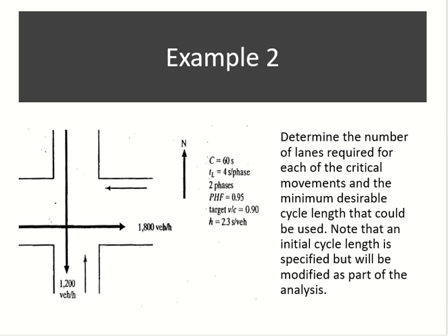Right now we are saying one lane here. So if there are 1800 vehicles, all of them will pass from one lane. So they will pass one by one. So all 1800 of them need some signal time, right? Clear? But if I make two lanes here, then I can pass two vehicles at a time.